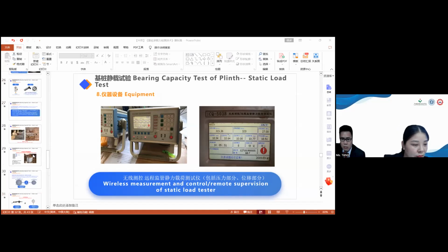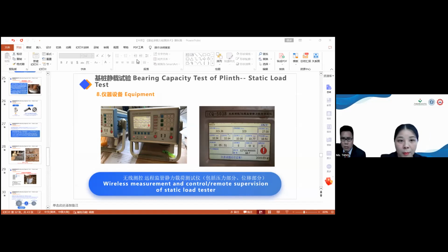One more question. For offshore bridge construction, what is the most efficient pile: group piles or monopile? Monopile. Because of the limited construction conditions, some kinds of piles cannot be constructed, and generally they use monopiles.